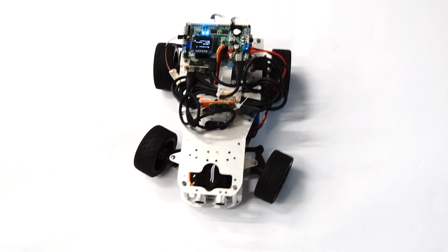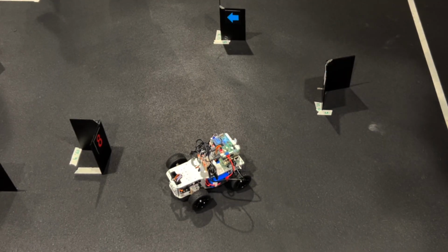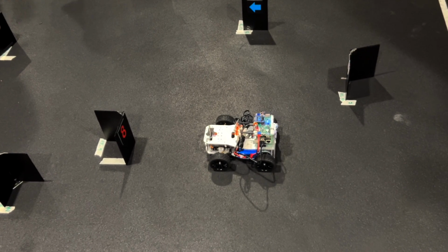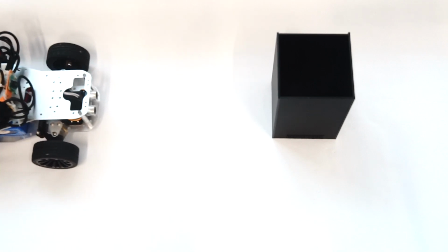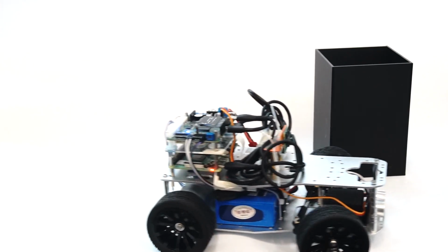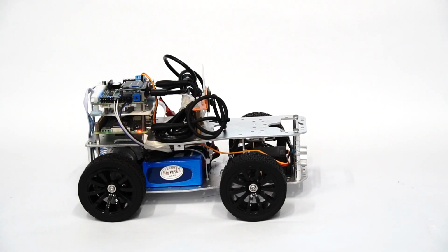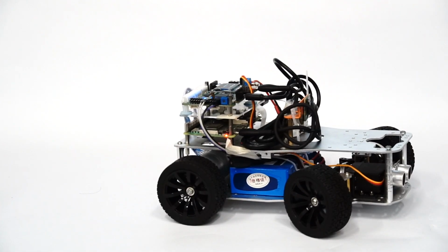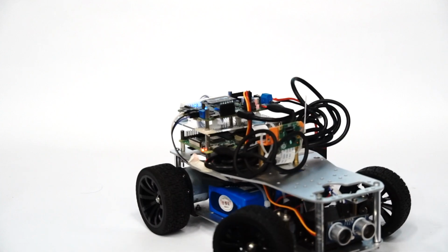The STM controller governs the movements of the robots. For the task to succeed, we need to ensure the robot's movement is precise and accurate. The Hall encoders were used to ensure that the robot moves the exact distance as instructed by the algorithm. A PID controller is used to ensure that both left and right wheels are moving at the same speed. To minimize the turning radius of the car, a 3-point turn is implemented to ensure that the turns are in place, which allows for better maneuvers to avoid the obstacles.